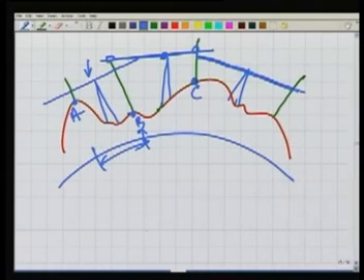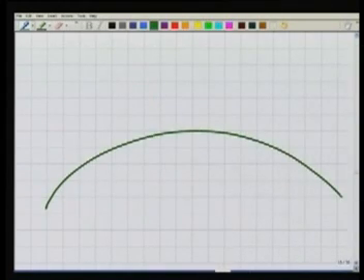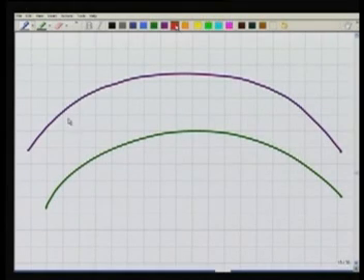So what we are doing, we are basically realizing, as you can see, if this is my mean sea level, I want to establish a surface which is parallel to the mean sea level. Over here, this is parallel to the mean sea level. This is what is desired, but we cannot establish it. So instead of that, what we are doing, we are establishing it in little pieces.